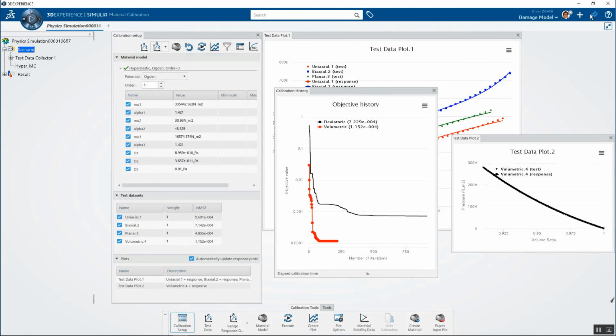So there are some other more advanced material models that you can fit. I would argue that if you're getting more complicated than elastic plastic or hyperelastic, maybe viscoelastic and hyper, and if you've got foam, maybe hyperfoam, it might be an opportunity for you to reach out and work with one of the technical resources at your reseller, or reach out directly to SolidWorks. But really a very powerful tool here, the Material Calibration app, and I hope you guys were able to see some of the power that's available inside of the SIMULIAworks. This really neat app on the 3D Experience platform is available with SIMULIAworks.